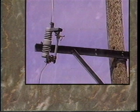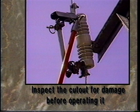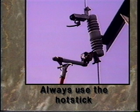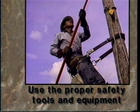Review. Properly install the cutout with an angle towards the pole. Inspect the cutout for damage before operating it. When possible, remove the load from the line before opening or closing a cutout. Always use the hot stick to operate the cutout. Replace blown fuses with new fuses of the same capacity. Always look away from the cutout when opening or closing it. Use the proper safety tools and equipment.